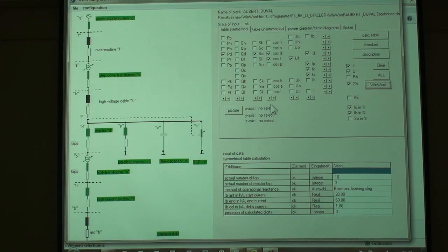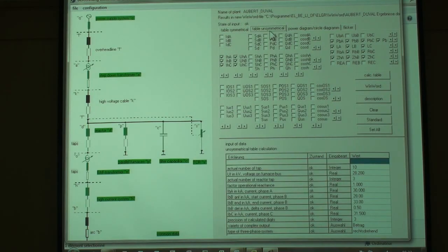But you put a furnace on operation, and after a while you see phase number 1 is extra worn out. There is too much wear. Or you see on the measurement from the ECS that even with the same set point, phase number 1 has a higher arc length because of higher voltage. So you can do unsymmetrical calculation.